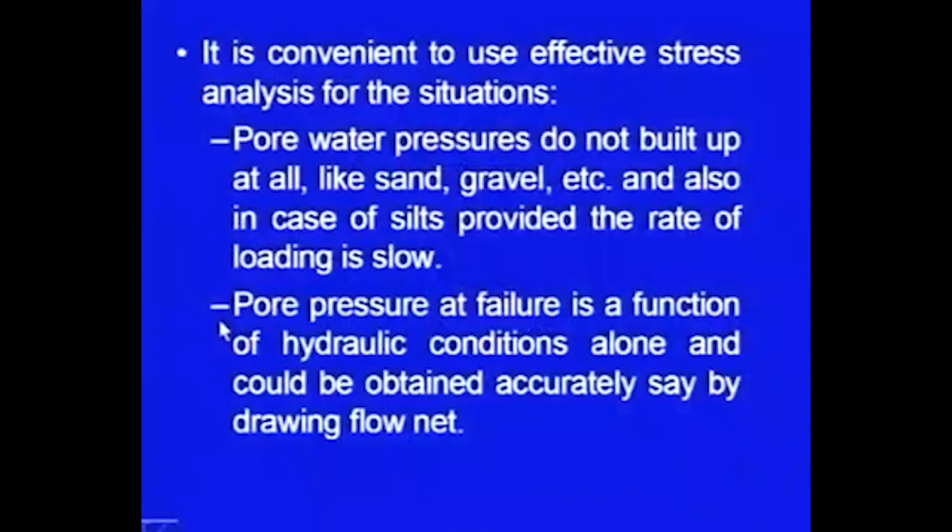Secondly, it is used where pore pressure at failure is a function of hydraulic conditions alone and could be obtained accurately, say by drawing the flow nets. So, this is an important point. We are accounting for the pore water pressure separately here by using the effective stresses. So, in the analysis we should be able to calculate the pore water pressure accurately.